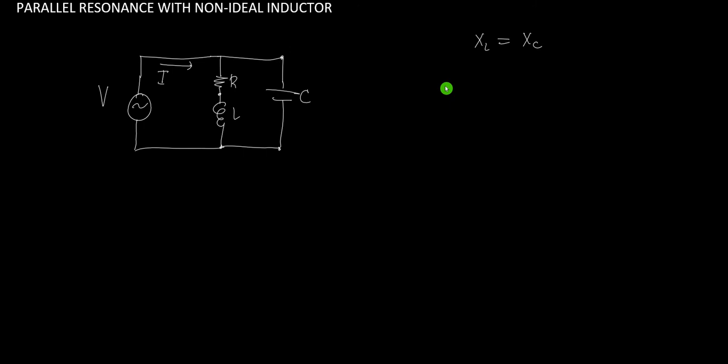Why? Because the circuit will not be a pure resistive circuit, because there's a difference between the Q here and the Q here. The Q of the capacitor is negative, and for the inductor, Q_L is positive. If you add them, it should be equal to zero when Q_C equals Q_L, and that's only true if they have the same voltage.